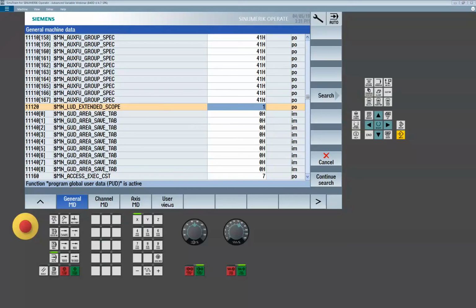And the save command is really powerful, but in turn, you could put somebody in a condition. I don't like to switch too much if I can avoid it. Like that little trick with the G500, I would never personally write a cycle like that because I wouldn't want to cancel somebody's offset. There's a much better way to do that.